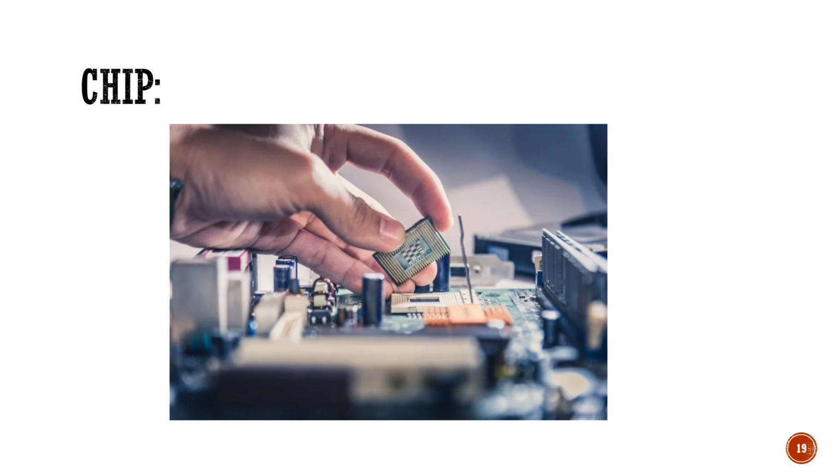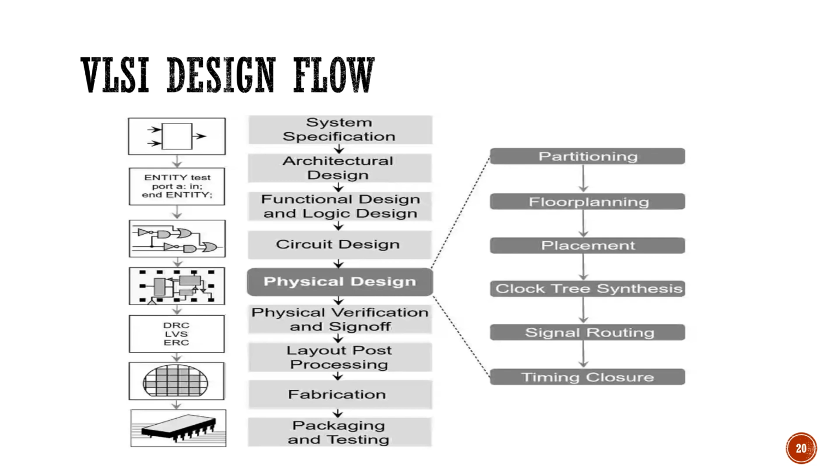Nearly 10 to 15 steps are involved. To consolidate, it starts with system specification, followed by architectural design, functional and logic design, circuit design, physical verification, where placement, routing, clock tree are involved, then verification and sign off, then post-processing, fabrication, packaging and testing in the VLSI design flow.